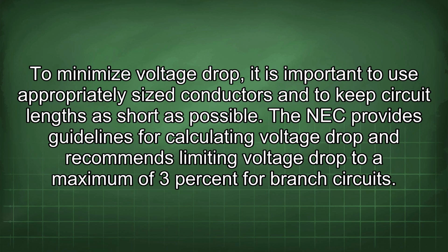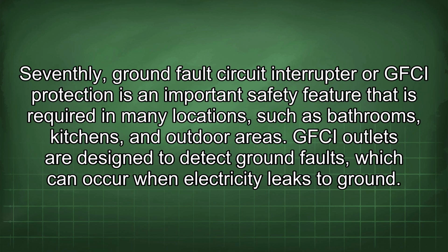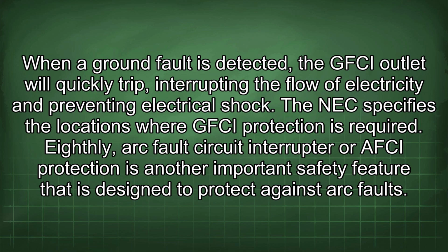Seventhly, ground fault circuit interrupter, or GFCI, protection is an important safety feature that is required in many locations such as bathrooms, kitchens, and outdoor areas. GFCI outlets are designed to detect ground faults, which can occur when electricity leaks to ground. When a ground fault is detected, the GFCI outlet will quickly trip, interrupting the flow of electricity and preventing electrical shock. The NEC specifies the locations where GFCI protection is required.